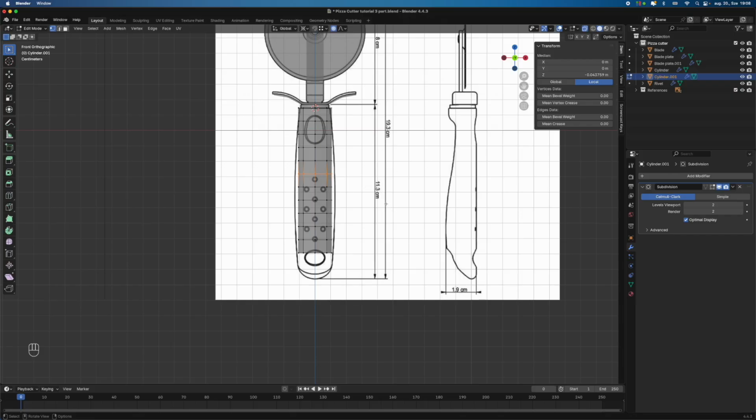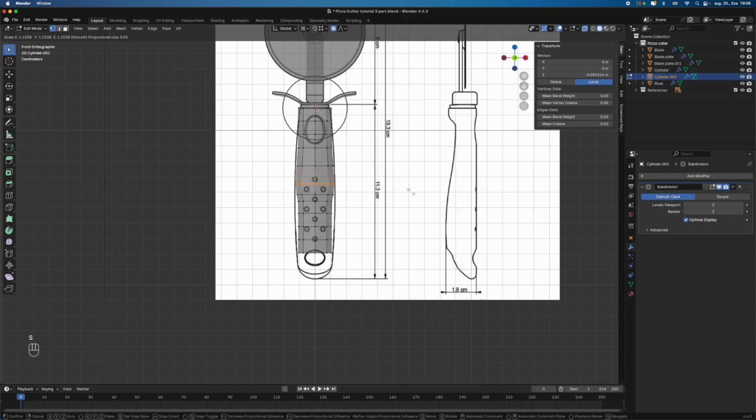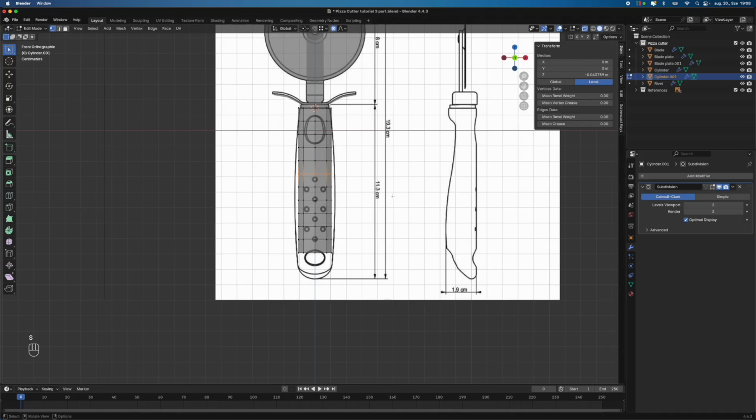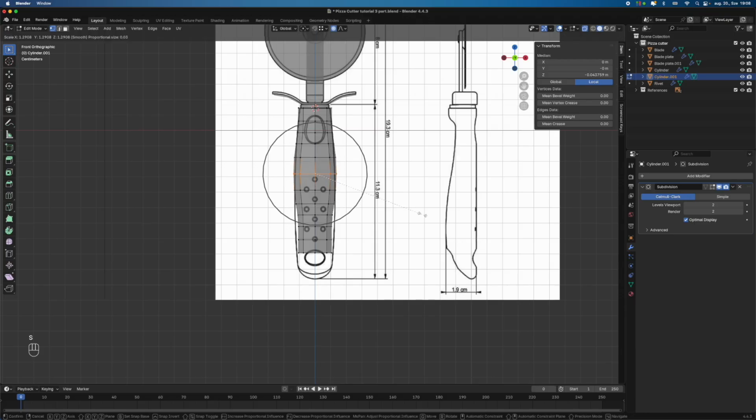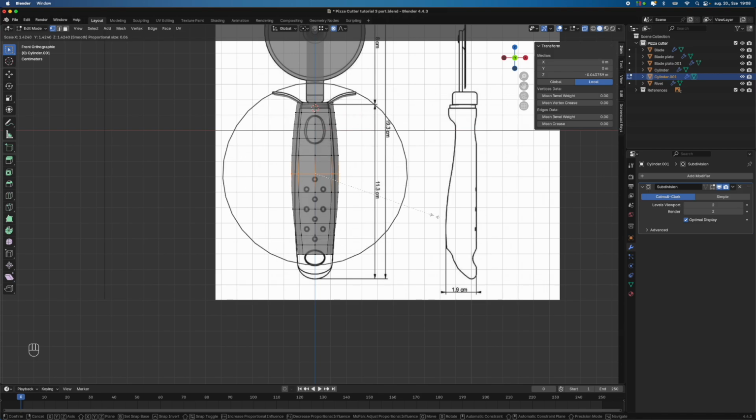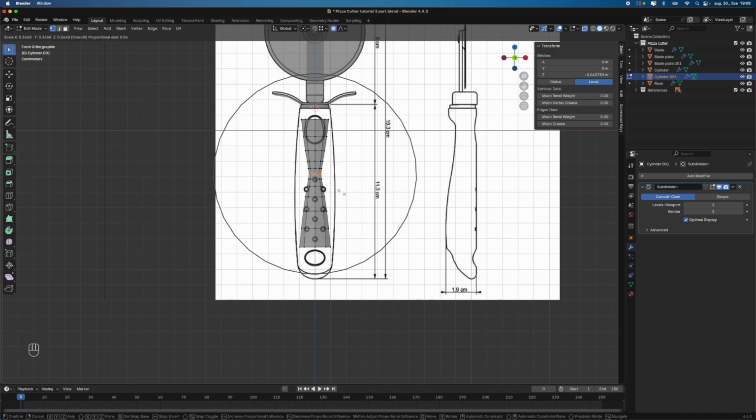And if you now hit S to scale, sorry, I changed it to bounding box center, how it was anyways when we left off. So with S I scale it, then with the mouse wheel we can change how much the falloff is, how much of the radius is affected by this proportional editing.